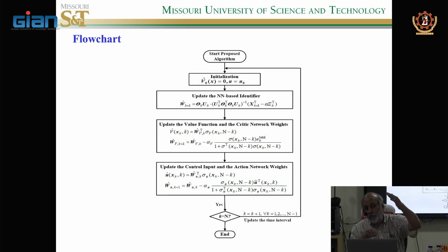So this is nothing to do with NCS, but NCS just uses the same thing, where we have the quantizer. I'm going to show you the quantizer. But before I do that, we have also incorporated actuator saturation. So remember, we talked about saturation in the quantizers. We can also have saturation for the actuators.